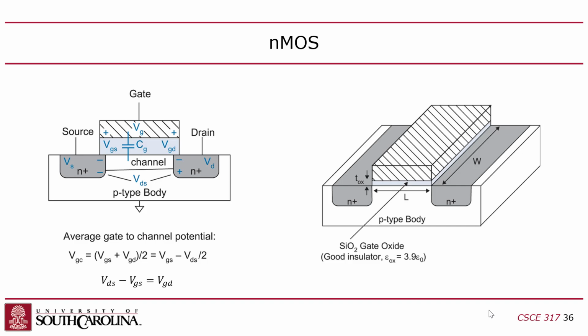So, your outputs are connected to one of these gates, and my goal is to charge up the capacitors that form the gates of my outputs, or to discharge them as fast as possible. And I can do that faster if I have more current, right? There are two options here. Either you have more current coming from VDD down through your PMOSs out, or you have more current coming back from the output gate down through my NMOSs down to ground.